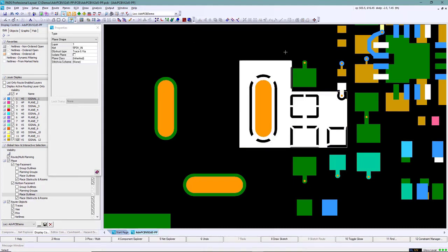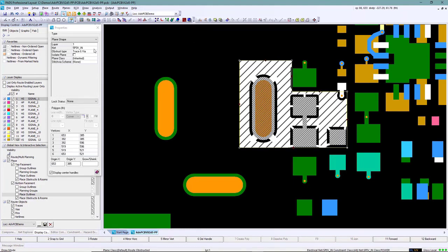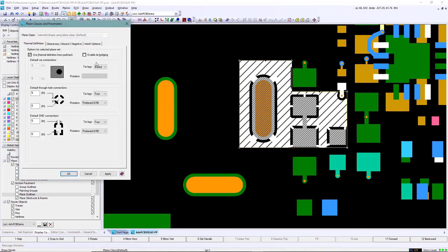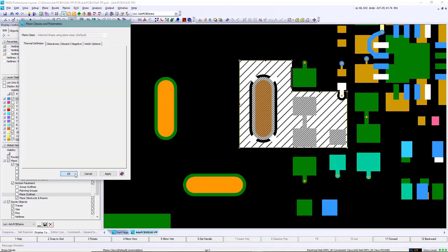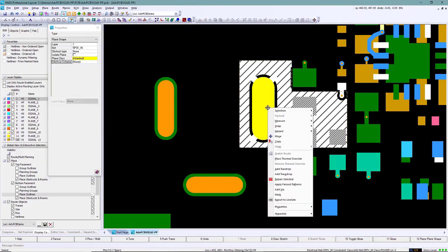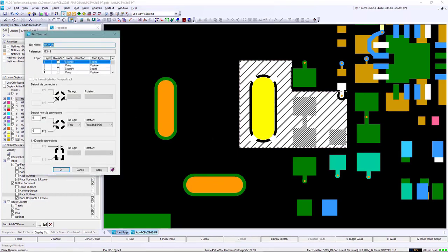One type of circuit design that requires special attention is power supplies. We need to keep inductance down and create copper areas that can handle high current. Doing this with traces is not the best option. Using planes and solid connections to pins is the simplest method.